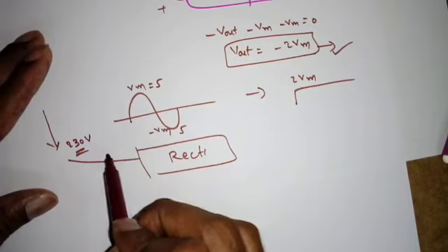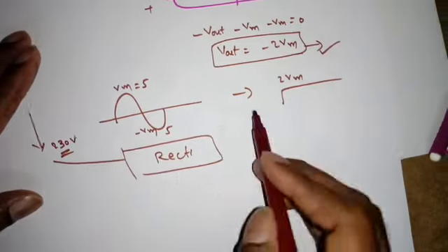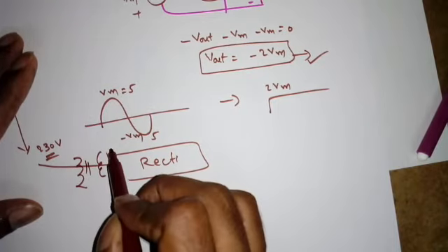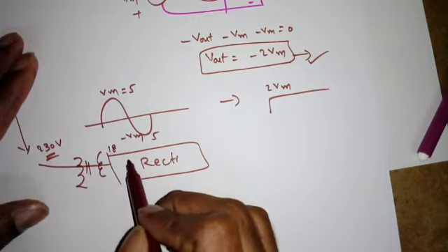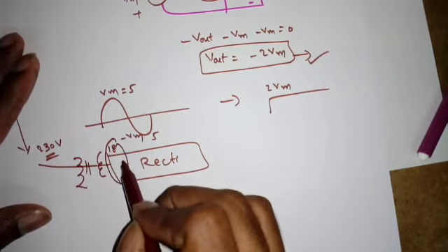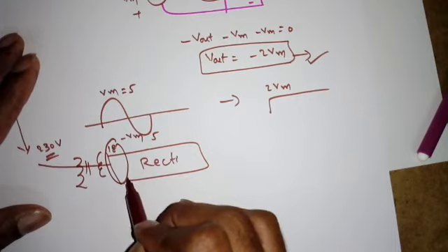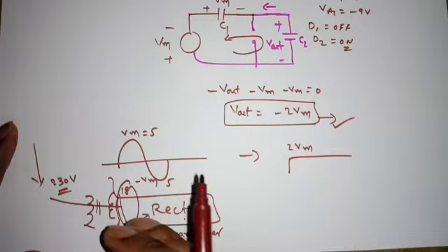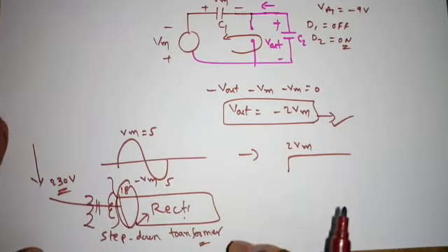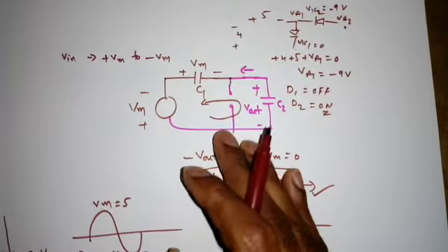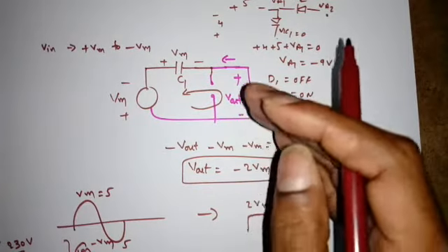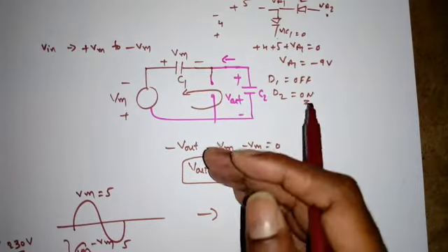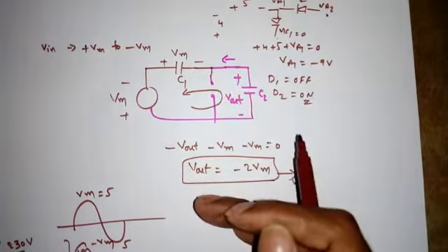So we have to use a step down transformer here, something like this, which will convert this 230 volt to 18 volts or 9 volts, etc. If I take that 9 volts, then we can give it to the rectifier, then filter capacitor, etc. So that will convert from AC to DC, right? And here we have some drawback, that is the capacitor takes some time to charge up to 2 VM, or we can say the moment we add some capacitances, transients will come, right?